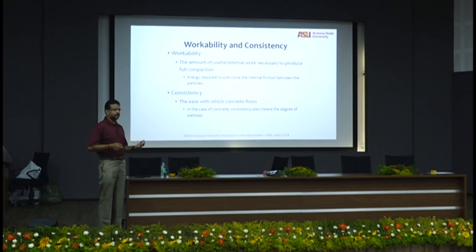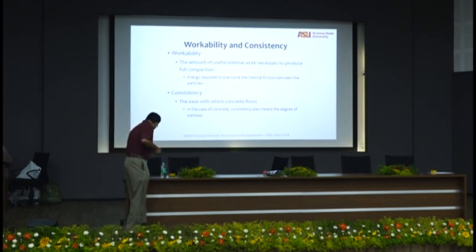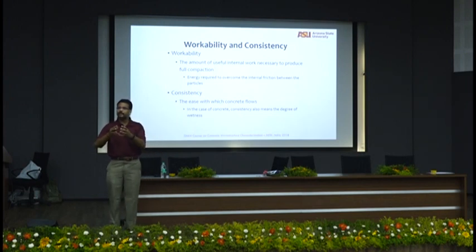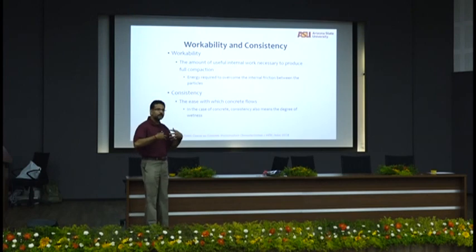When you talk about workability of concrete, workability is basically the amount of internal energy you need to produce full compaction, or the energy required to overcome the friction between particles. You want to make the concrete flow.